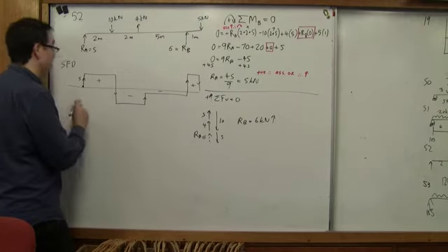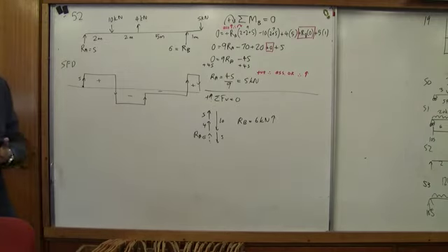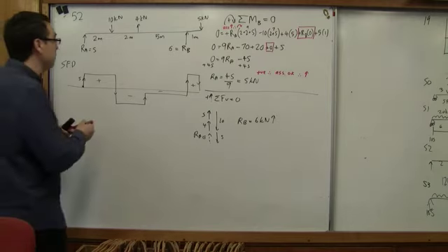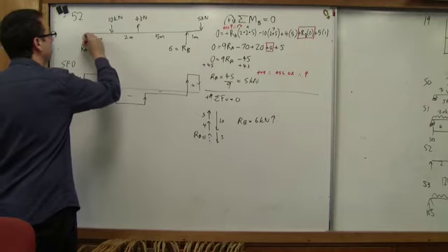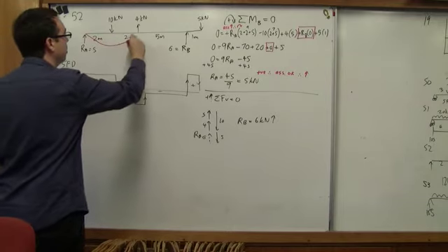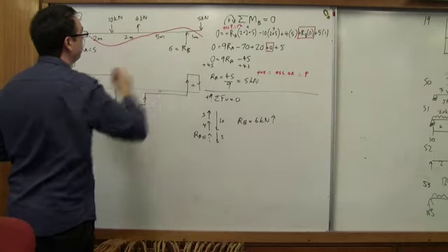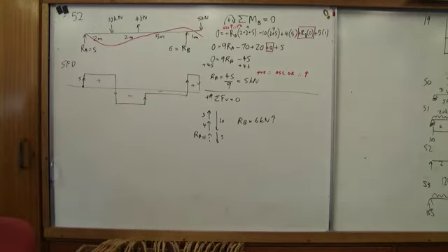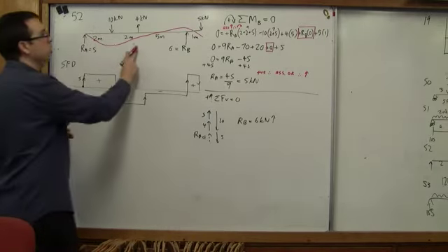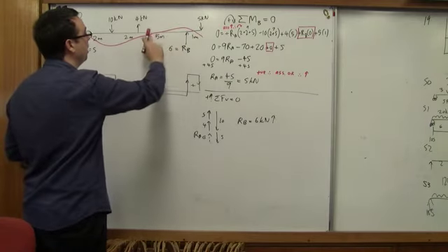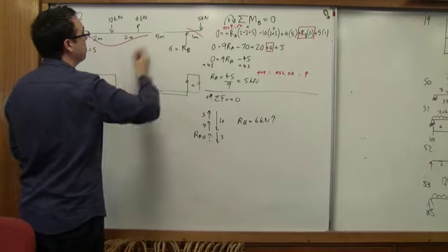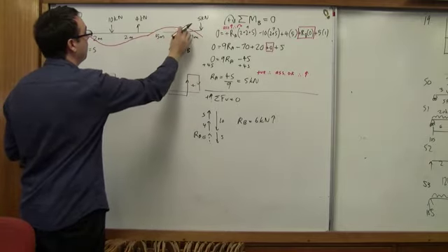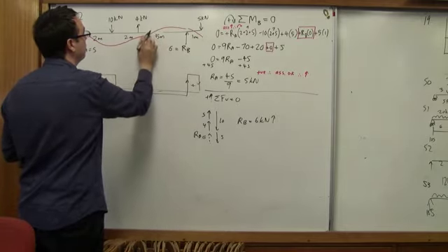So, what is our bending moment diagram going to look like? What a lot of people like to do is they like to imagine, how is this beam going to bend? And so, well, if you've got this pushing up and this pushing up, you're going to have something that goes down, then up a little bit, and then like that. That's probably what it's going to look like, something along those lines. Because we've got this 4 pushing up here, then you have more pushing it up later. So it's going to probably push up even a little bit higher, a little bit steeper like that. Something along those lines. Smoothing this out.